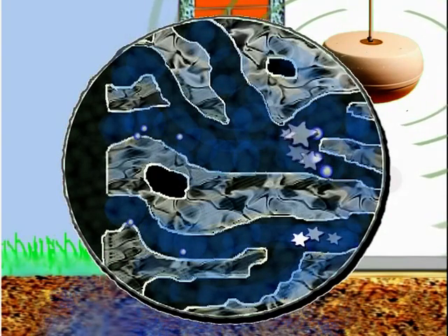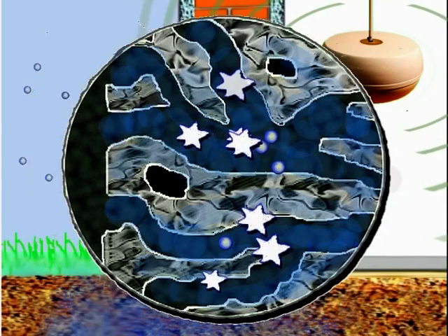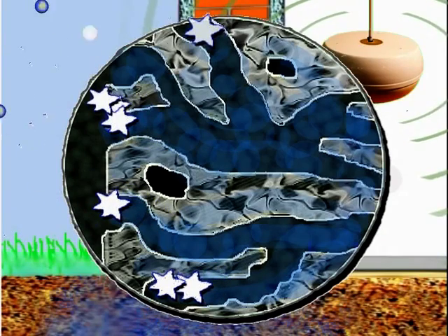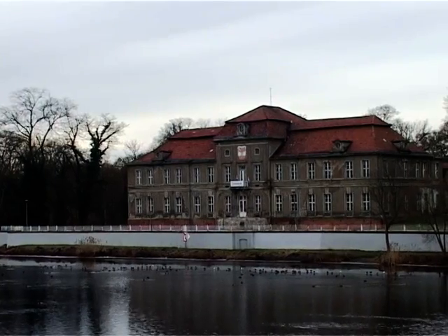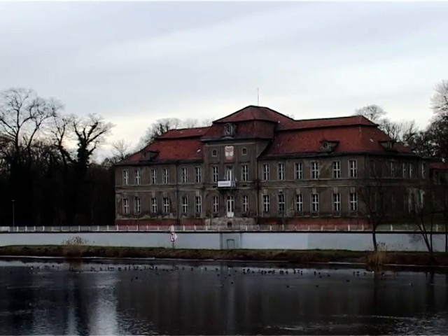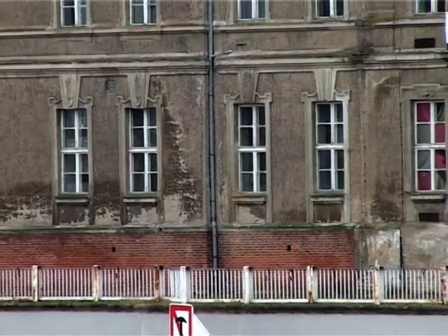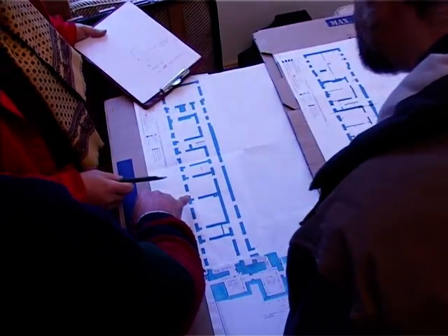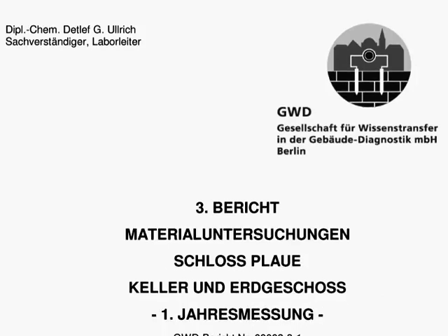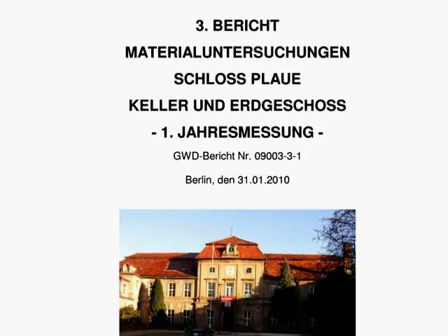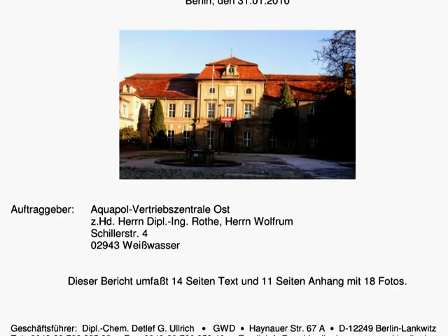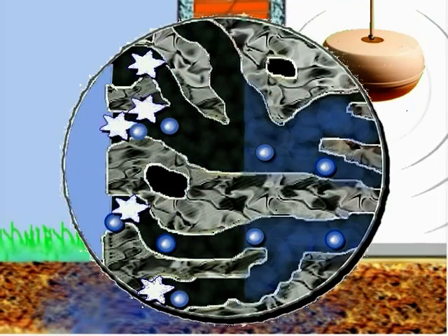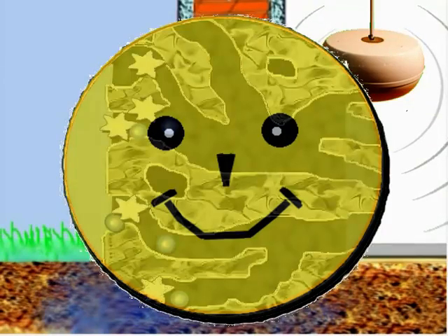During the drying out process in the evaporation phase, the salts dissolved in water are transported to the plaster zone, where they partly crystallize because of the evaporation process. The evaporation process, along with the crucial process of partial desalination, usually takes 3 to 12 months. This was confirmed by exact salt measurements in an expert report based on a major project in Germany. The fewer salts there are in the basic structure of the building, the less is the residual moisture in the wall.